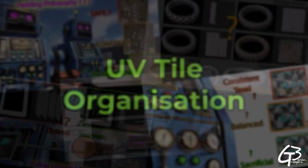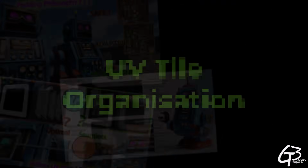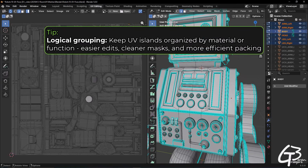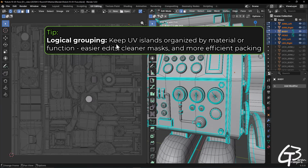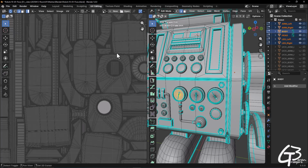Now let's dive into the third set of principles, how we organize UV islands across the texture space. This part is all about structure, efficiency, and readability. Organize your UV islands by material type, shader assignment, or functional grouping. Avoid random scattering. It makes 2D editing easier and helps minimize visual texture bleeding.